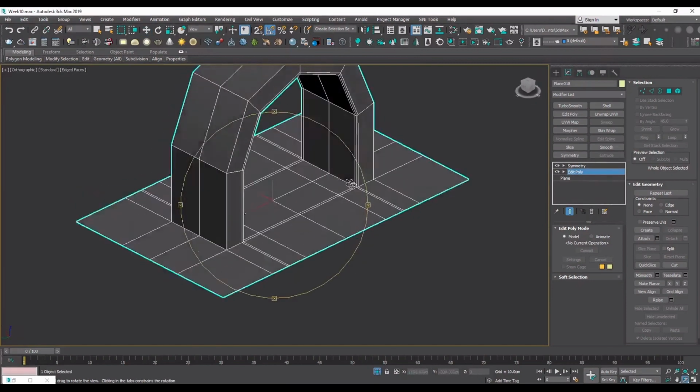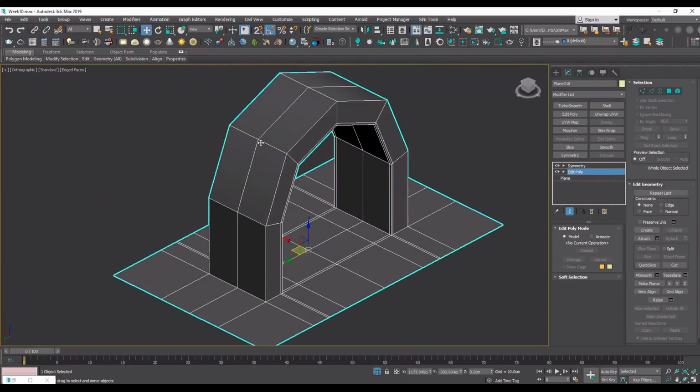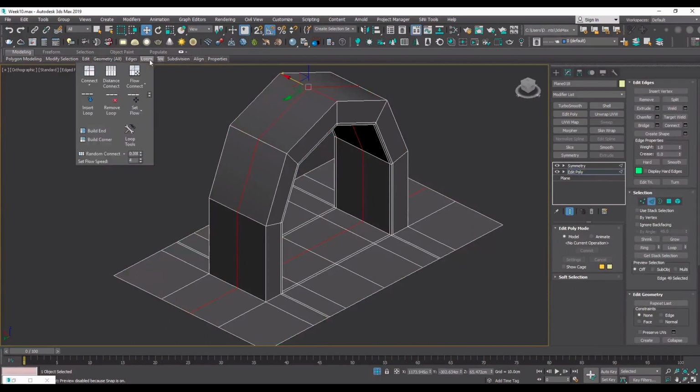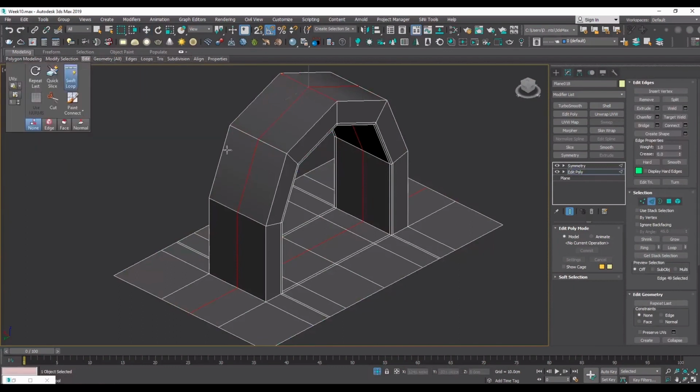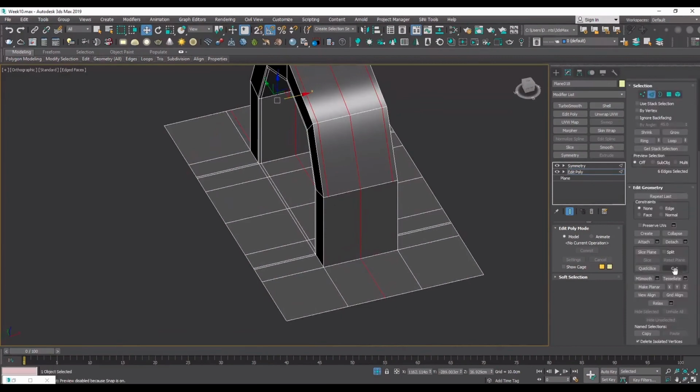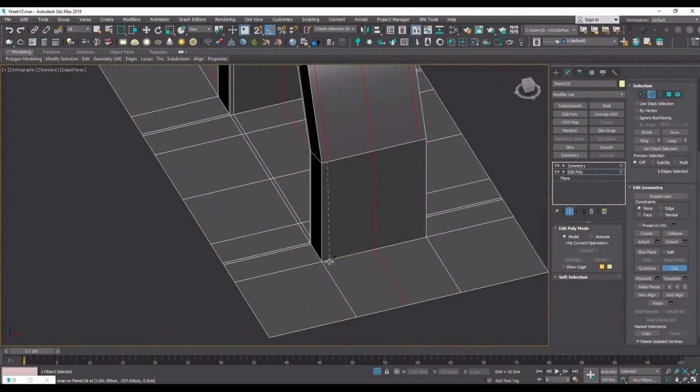How? I keep my symmetry and just, again, select my Swift Loop tool and add the loop there and just rotate, get to the part that is problematic, and then pick up my cut tool and manually cut it through where I want. And just like this, it's going to work. Just adjust it a little bit.